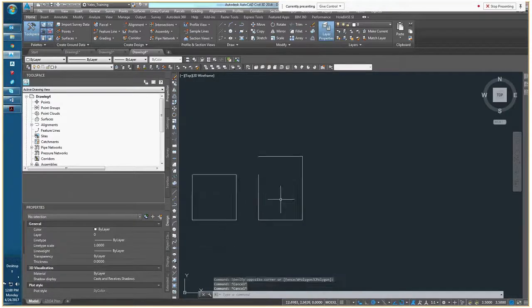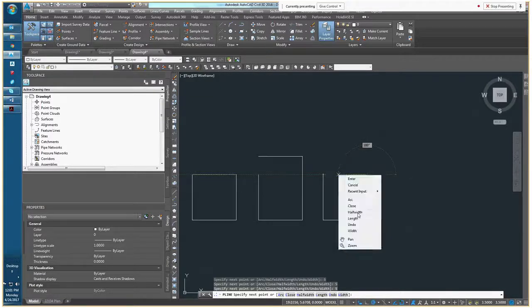represent. So what I'd like everybody to try to remember is that when we're drawing polylines that we want to be closed, whether it's for a structure or a wetlands boundary or any other purpose, if it's intended to be closed, then before you click over here on your last vertex, simply right-click and use the Close command within the right-click menu.